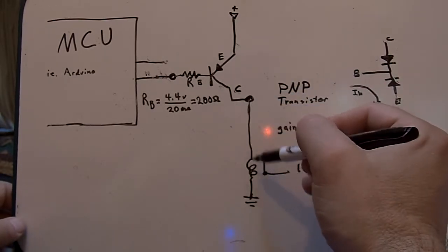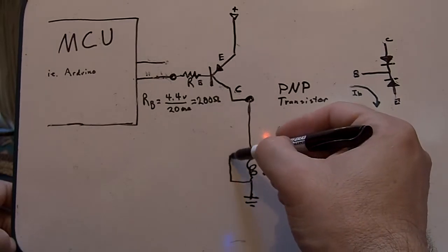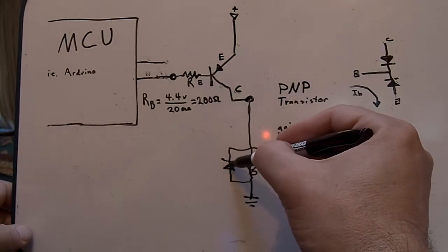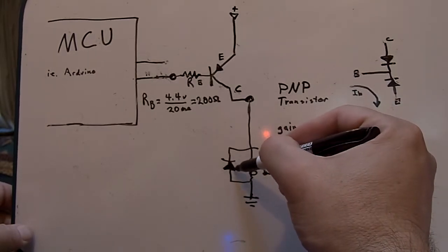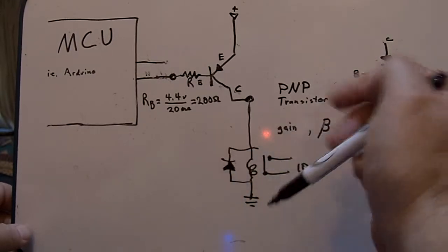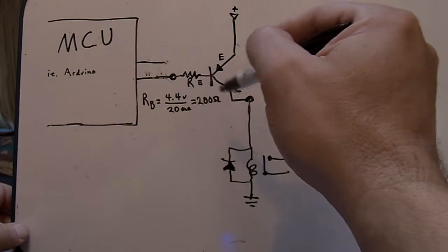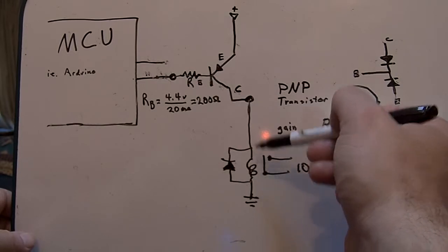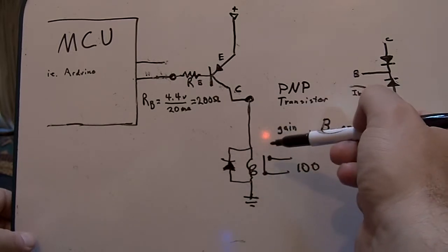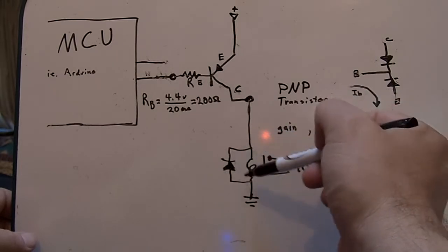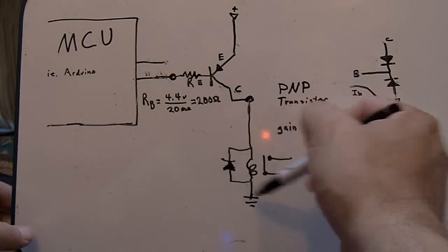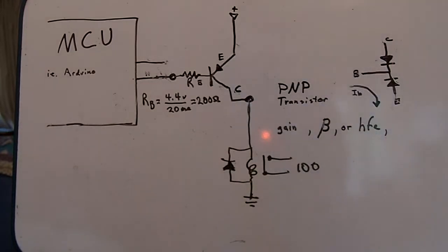And now what's normally done is they put what's called a snubber diode across this. This diode's in backwards deliberately. And what it does is when this transistor, say, abruptly stops letting current through, the current field will collapse around this coil and produce a back EMF, a reverse voltage across the circuit, which this diode will short out for you. This diode will return it for you and get rid of it. That protects the transistor.